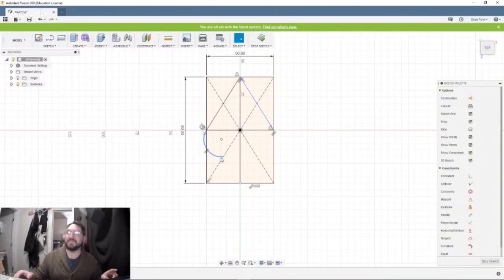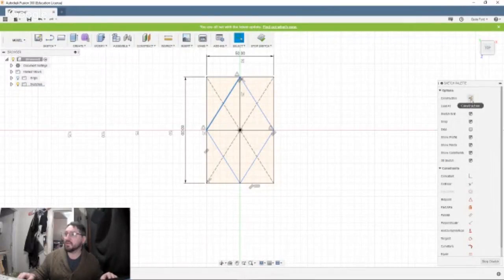I was like, let me do a straight tool. Stop it. Okay, I see what I was doing. Yes, I should have thought of that, because you're right, I am using the spline tool. All right, so what you can do is take this, go over here and make it a construction line, which I highly recommend because it takes less time to load a construction line than it does to load a spline, especially if you're not planning on using said spline.